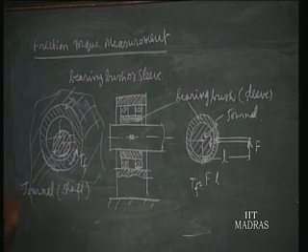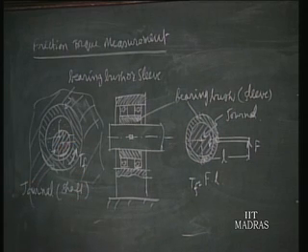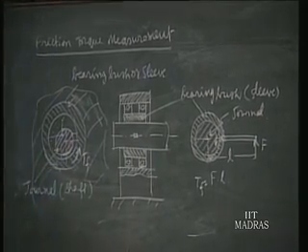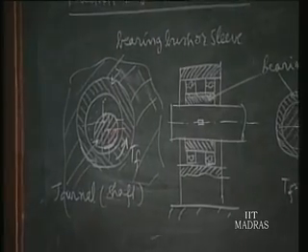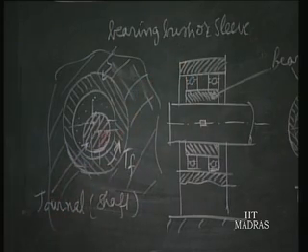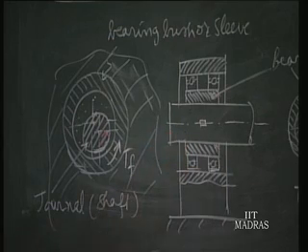So the frictional torque is normally absorbed by the wall, since the sleeve is press fitted to the wall. The phenomenon here is, due to the friction torque, the sleeve will try to rotate along with the shaft, but it is not allowed since it is press fitted. But when we want to measure that friction torque, naturally we do not fix it to the frame, as you have learnt in the reaction principle. Here we mount the sleeve on 2 ball bearings, called trunnion ball bearings, so that now the sleeve is allowed to rotate in the same direction as the journal.